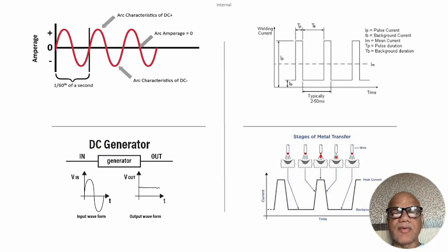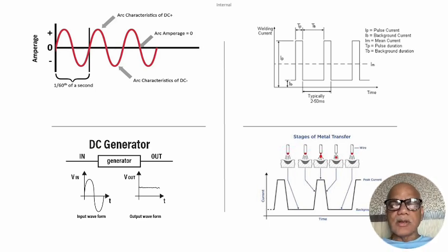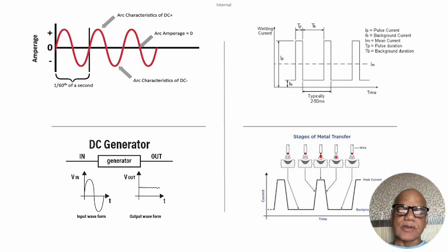Plus this higher frequency also helps in improving the arc force, and that is essential when we are doing root runs or complex runs where root fusion gets difficult, where you have one side edge preparation and the other side vertical, still it becomes difficult and you can use it.